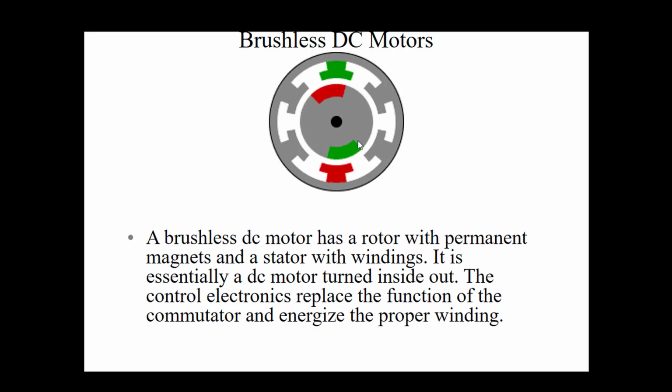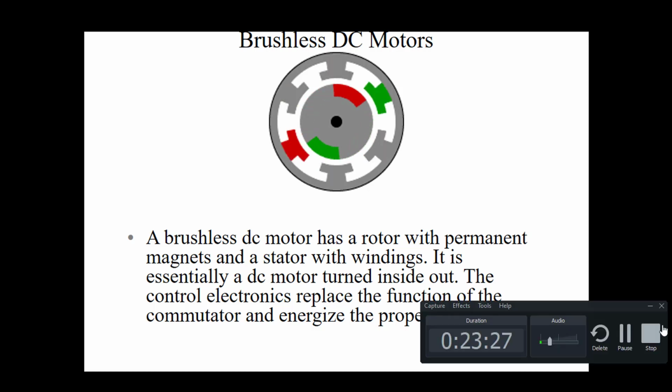That is why I take this diagram. Here in the brushless DC motor, all the phases are generally energized and they produce a rotating MMF, and that rotating MMF causes magnetic interlocking, just like that synchronous machine, and it rotates, right? So that is the case here.